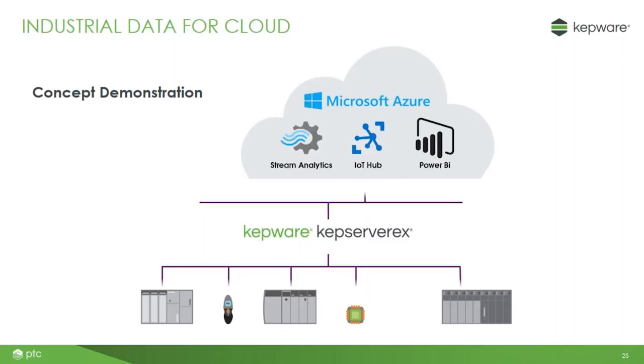Excellent. Thank you so much, Ray. That's great. So the interaction between KepServer and Azure is extremely simple to set up. Essentially, we're interacting with, as Ray noted on the slide, the Azure IoT Hub. We have a couple different points of connection between KepServer and the hub. We can push data to it using MQTT, and we can push data to it using our REST client agent for HTTP, and either work really, really well.